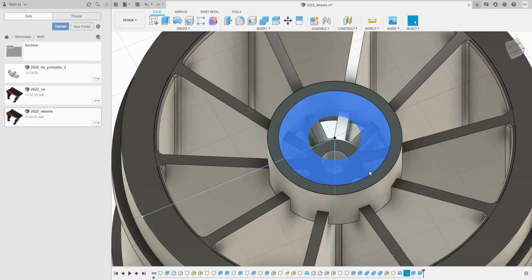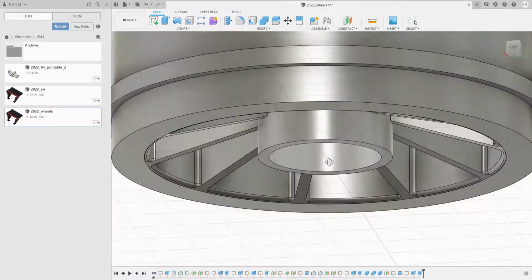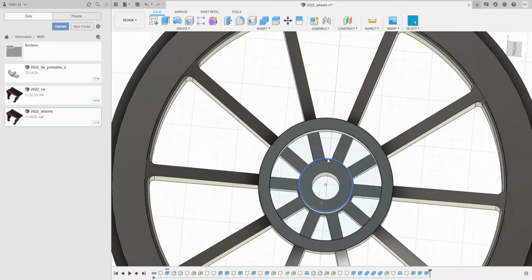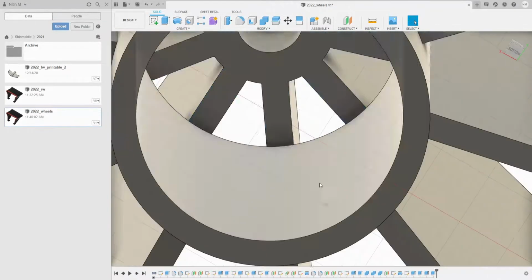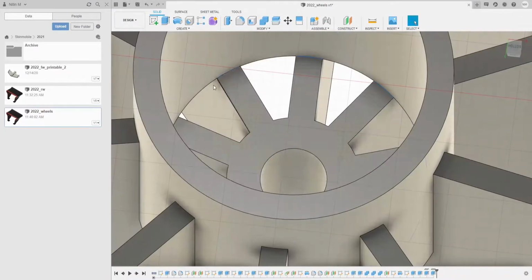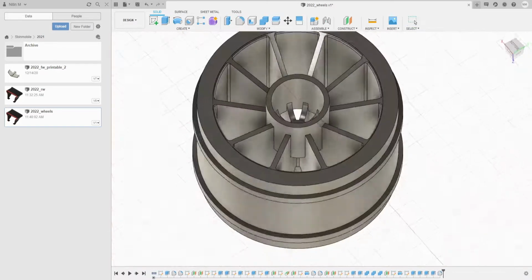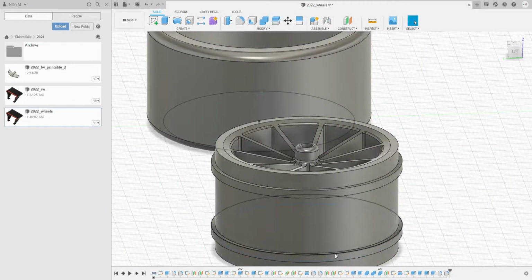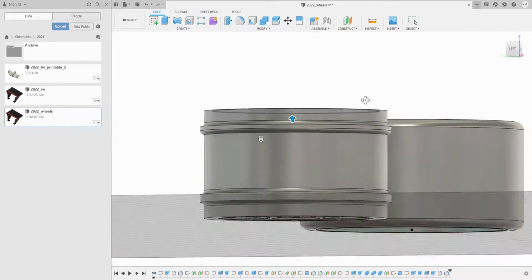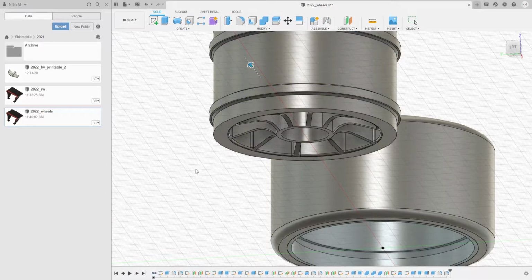This is an adapter for the front axle which will assist in keeping the tire aligned. I then trimmed down the wheel nut section and filleted the sharp edges again. This is more to help with printing well, as vertical fillets do not need supporting so that the wheel prints fully supportless. I also chamfered the locking grooves so that they fit easier when I assemble the tires.